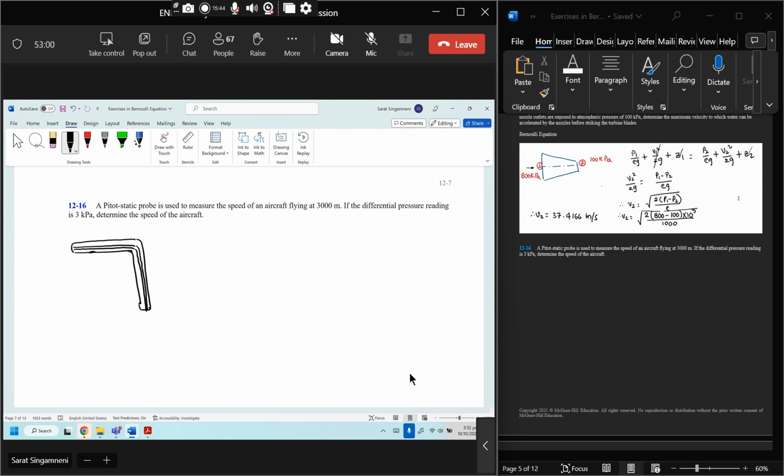There is a hole here and there is a hole there. And these two are connected like this, which will give you the P static pressure. We saw a tube and just a vertical pipe attached. It measures the static pressure in the flow. That is P static. And this stagnation pressure here, that is measured by connecting this to a gauge. So this is the P stagnation.